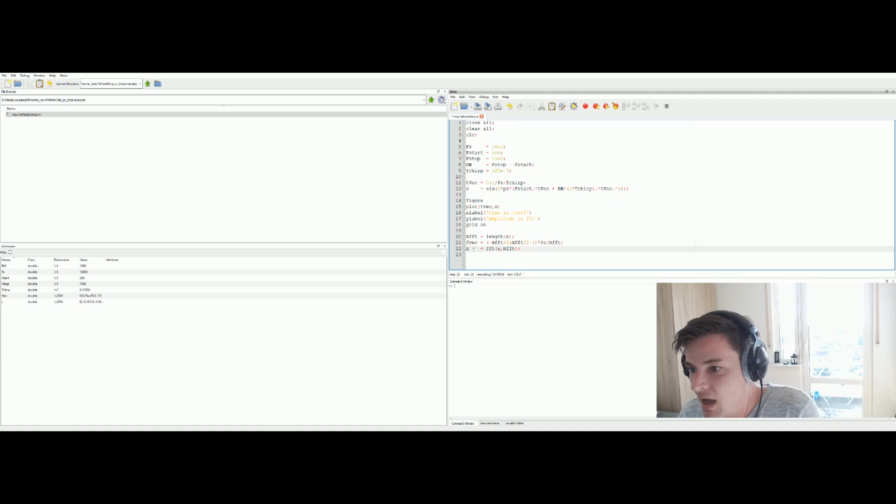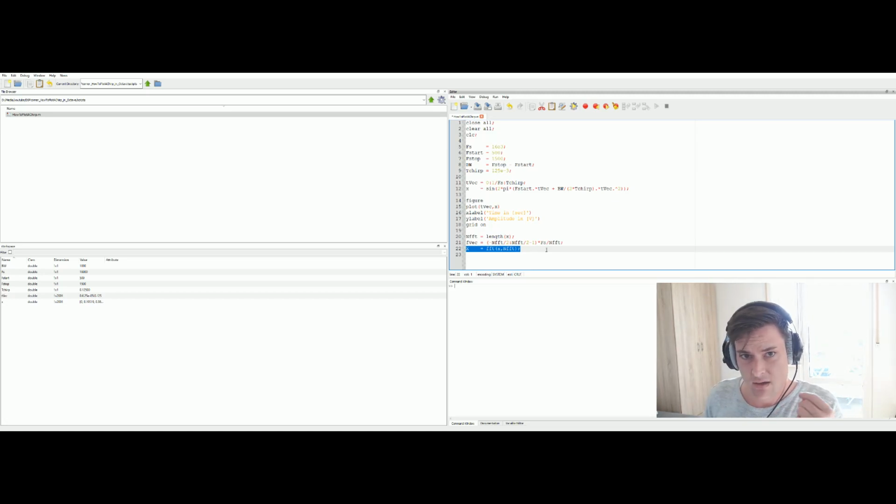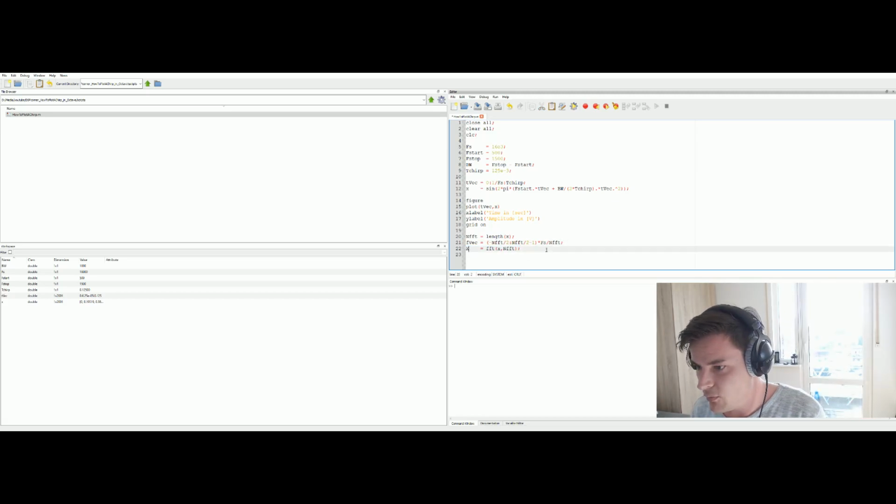The output will be a complex signal here in X, but the FFT arranges our frequencies in a way that we have first our positive frequencies and then our negative frequencies, and for plotting we want to have our negative frequencies on the left side and our positive frequencies on the right side. Therefore we use the command fftshift to rearrange the complex output of the FFT command. So now everything is calculated and we can plot our result.